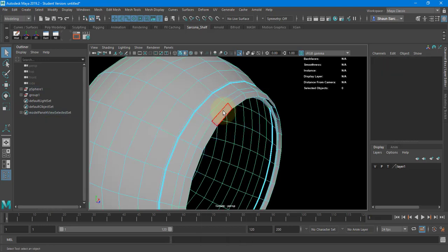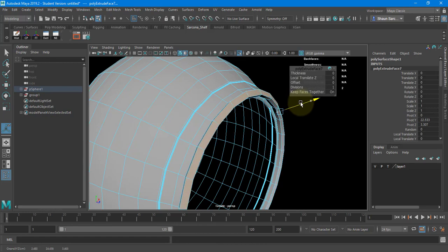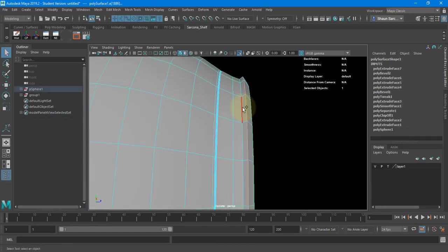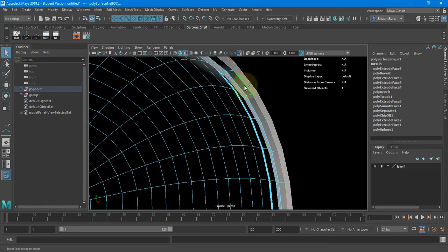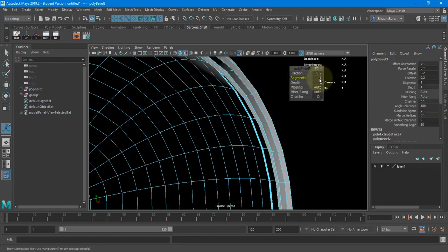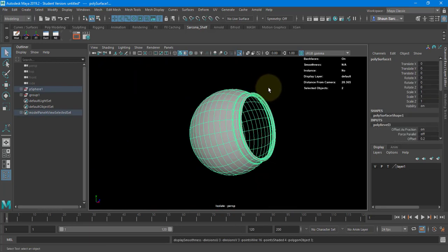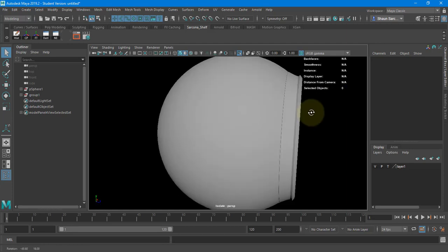I think I want to maybe extrude this a little bit more, so I'm just going to extrude that and push that out some, just to give that a little bit more detail. And then bevels all around. Everyone gets a bevel. Here looks like it's pretty tight. I shouldn't need a bevel there. 0.2 and 2 segments and object mode and 3. So that looks pretty detailed.